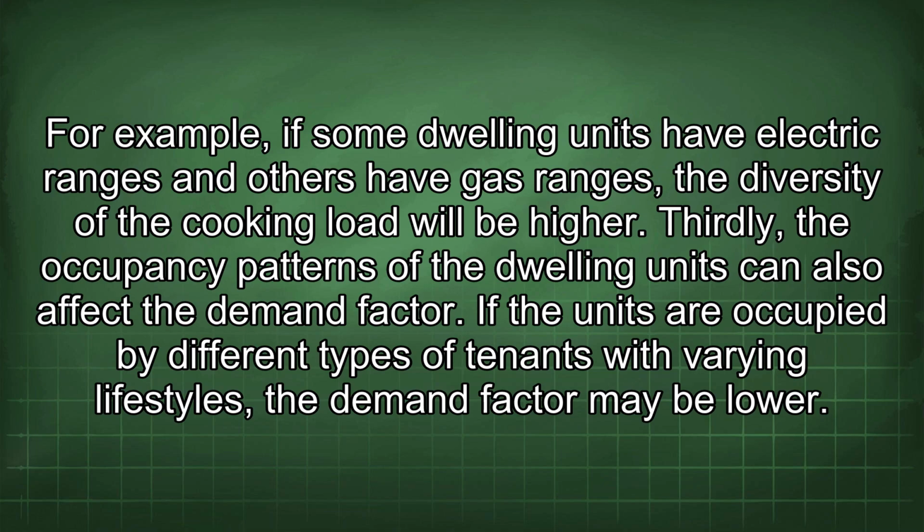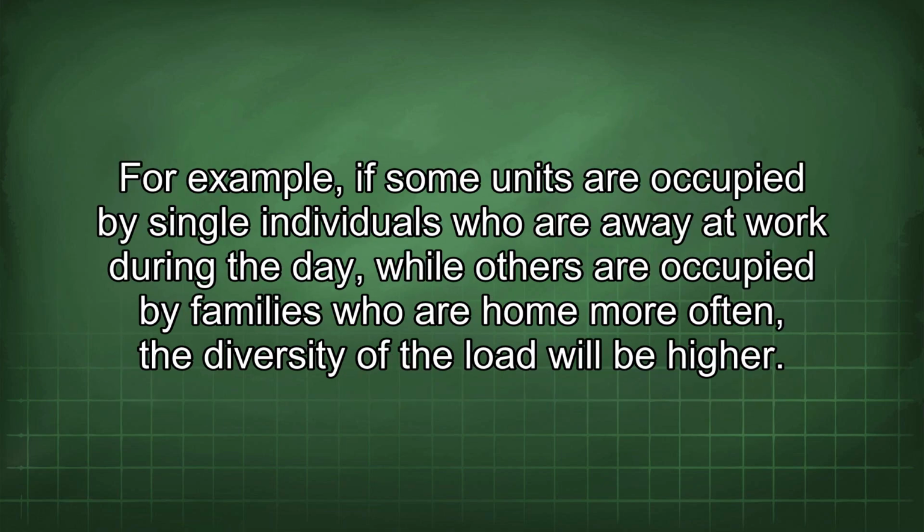Thirdly, the occupancy patterns of the dwelling units can also affect the demand factor. If the units are occupied by different types of tenants with varying lifestyles, the demand factor may be lower. For example, if some units are occupied by single individuals who are away at work during the day, while others are occupied by families who are home more often, the diversity of the load will be higher.